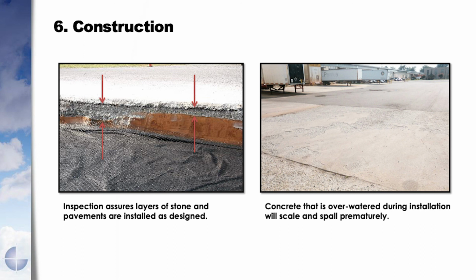And it looks great when you water the top of it when you're done, but what happens is you lose all the strength on the surface of the concrete, and you get this scaling where the hard surface flakes off, causing this premature failure of the concrete. I think this concrete here was only 3 years old at the time I took this photograph. Many times less than what it should have lasted.